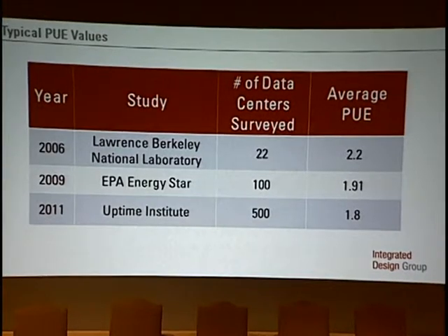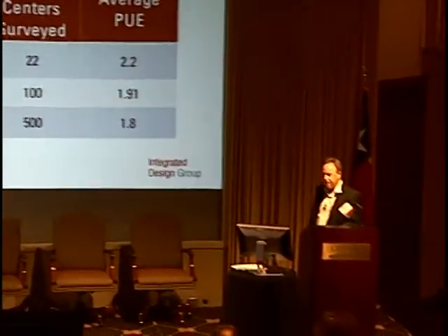The best PUEs are the ones you just saw, typically 1.3 down to 1.04, typically gotten by companies that are willing to greatly expand their IT space conditions. So, you just heard eBay will allow up to 95 degrees in some of their spaces. The higher you can allow, the more you can expand that temperature range and humidity level, the lower you can get your PUE. That gives you the more hours that you can run on economizer cycles and not use mechanical cooling.